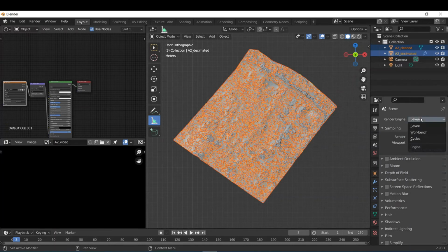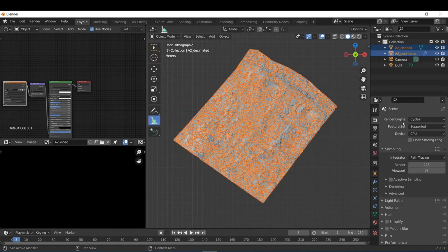You'll want to make sure your render engine is Cycles. If you want to try GPU compute, feel free if you have a dedicated graphics card for that sort of thing. So you can see in here we have a lot of options, and a lot of people have their own preferences based on their own machines. For us, we're going to set render to 8. Under light paths, maximum bounces, we're going to set that to 2, while everything else is going to be set to 4.